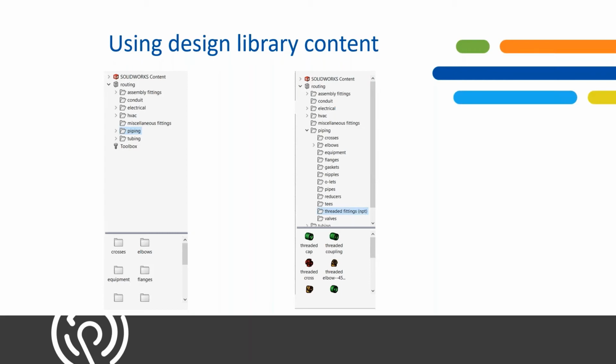And it will even specify this in your SOLIDWORKS routing manual. If any of you have any kind of SOLIDWORKS routing manual, if you've been through our training, in the back of the book, every book is a little bit different with the pages, but it's most likely in the back of your lesson 10. SOLIDWORKS will give you a structure of how you should structure your design library components. It even says the failure to follow this procedure will cause problems within your routing and your general assemblies because the file structure is different.